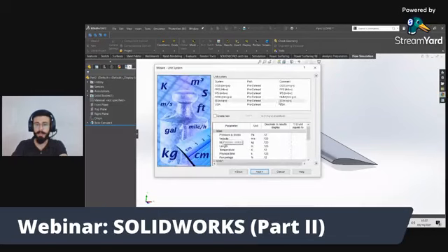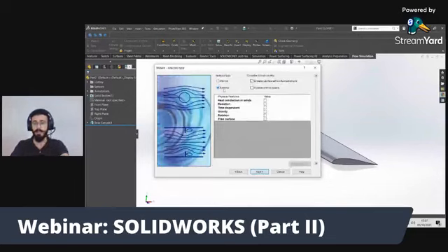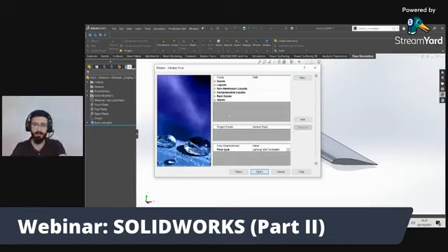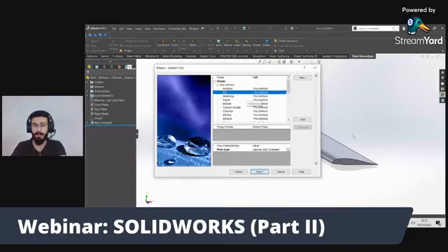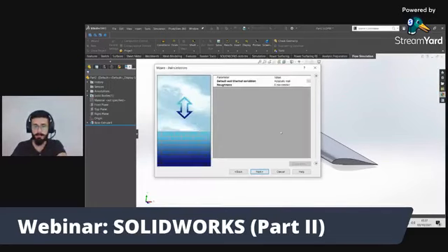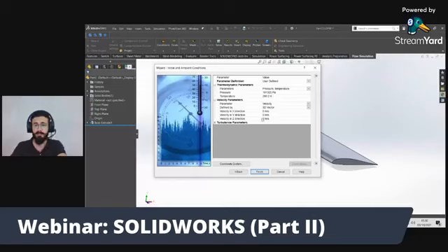Okay, next, from here you will select the unit system. I have selected this. Next, and then there are two types of flow simulation: external is for winds, for vehicles, or everything. Internal is for pipes, flow of water inside the pipes. So we are doing external, along the surface. What type of fluid are we using? It's a gas and it's air. Just add it here. Next, next, and here we are going to add velocity, x-axis. Let's suppose 35. Finish.